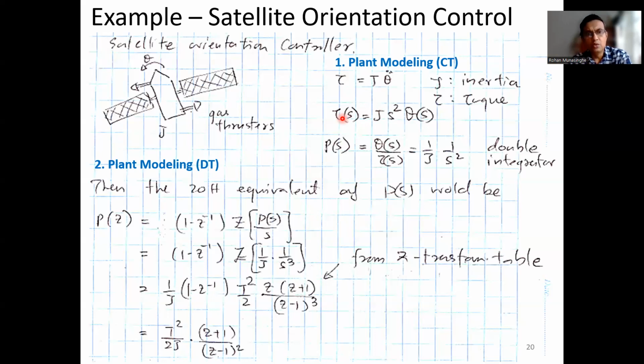Which means you have the satellite, you give it a torque, or thrust becomes a torque here, right? And then the satellite swings. So the torque is the control signal. It's not the reference, right? If the satellite moves, the reference is actually the angle, the heading. Here, the torque is not a heading. Torque is just an actuator signal, some control signal. It's not the reference input.